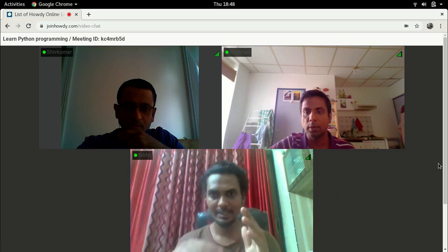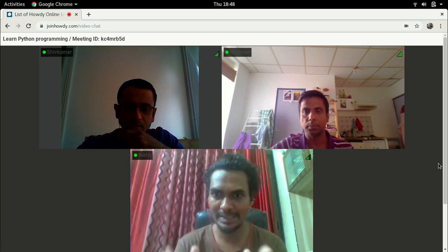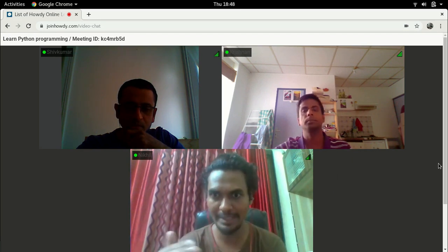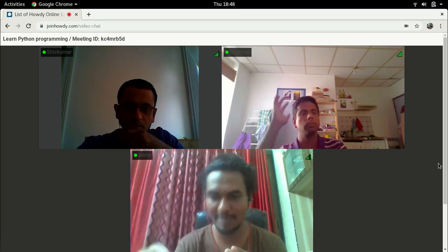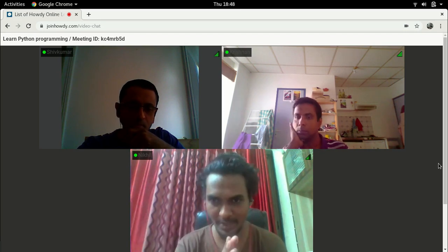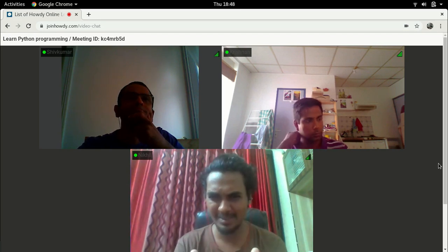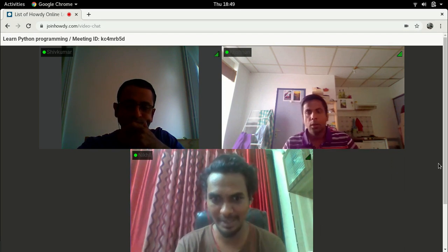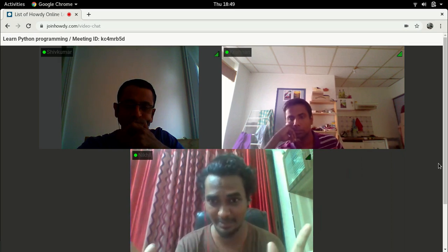Basically, the plant is a boost converter, and I want to design a proportional integral controller. I want to compute Kp and Ki values so that for whatever step input, it will reach the steady state in this amount of time and not go into overshoot. So this is the main idea. It is a very basic problem that we solve in college, but since we are used to MATLAB and Simulink nowadays, we don't go into much detail and equations. Simulink does everything for us.